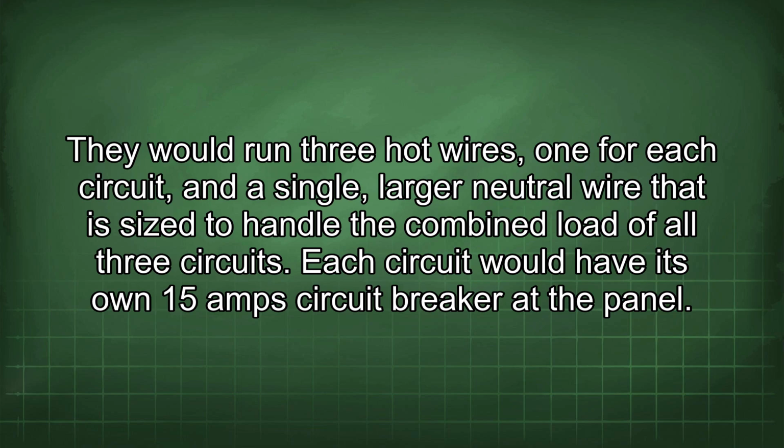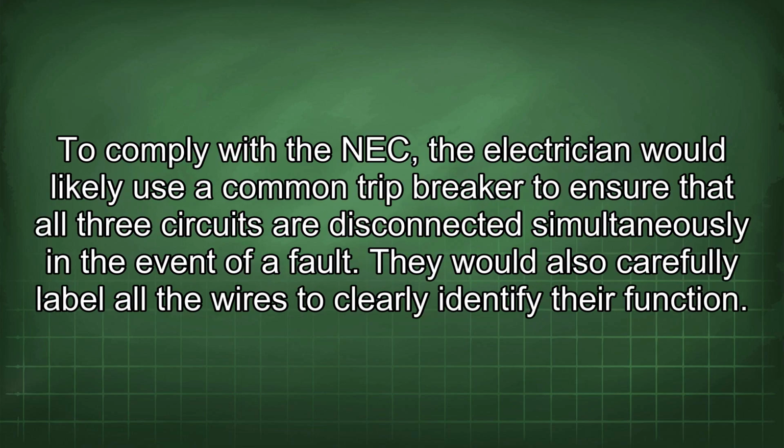Each circuit would have its own 15 amp circuit breaker at the panel. To comply with the NEC, the electrician would likely use a common trip breaker to ensure that all 3 circuits are disconnected simultaneously in the event of a fault.